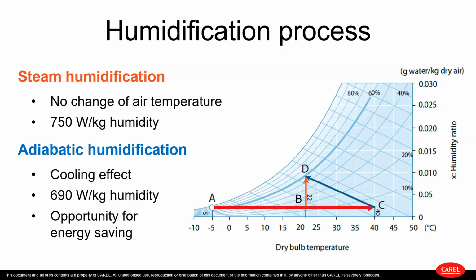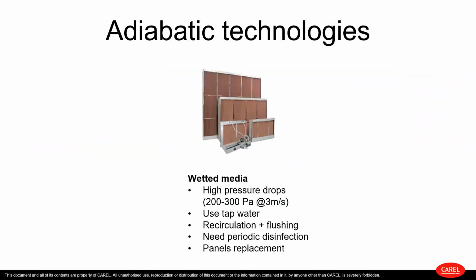As well, if we use the adiabatic systems to make evaporative cooling in summertime, we can decrease the temperature inside the painting booth simply by spraying water instead of using mechanical systems. These technologies providing adiabatic humidification are pretty common in the market.